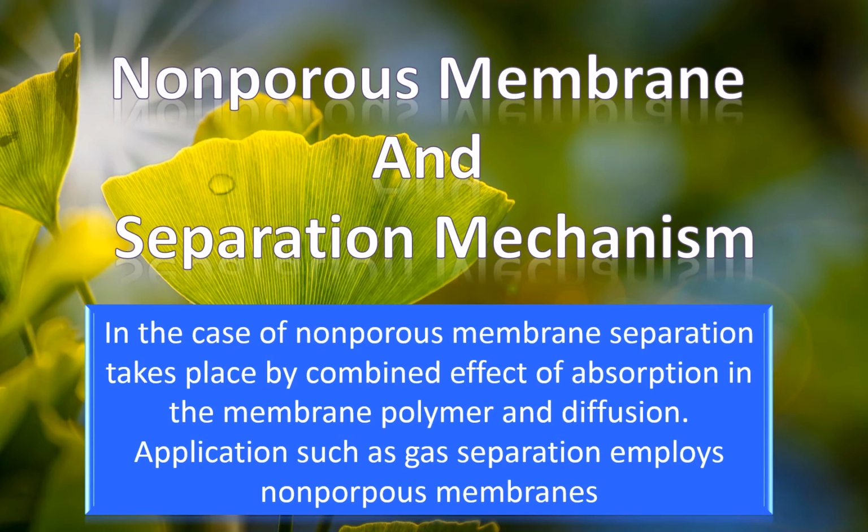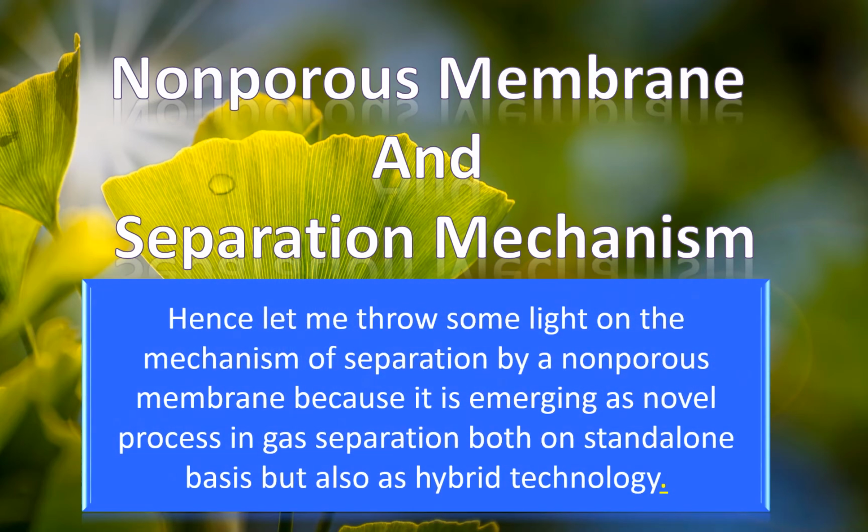Applications such as gas separation employs non-porous membranes. Hence, let me now throw some light on the mechanism of separation by a non-porous membrane because it is emerging as a novel process in gas separation, both on standalone basis but also as a hybrid technology.